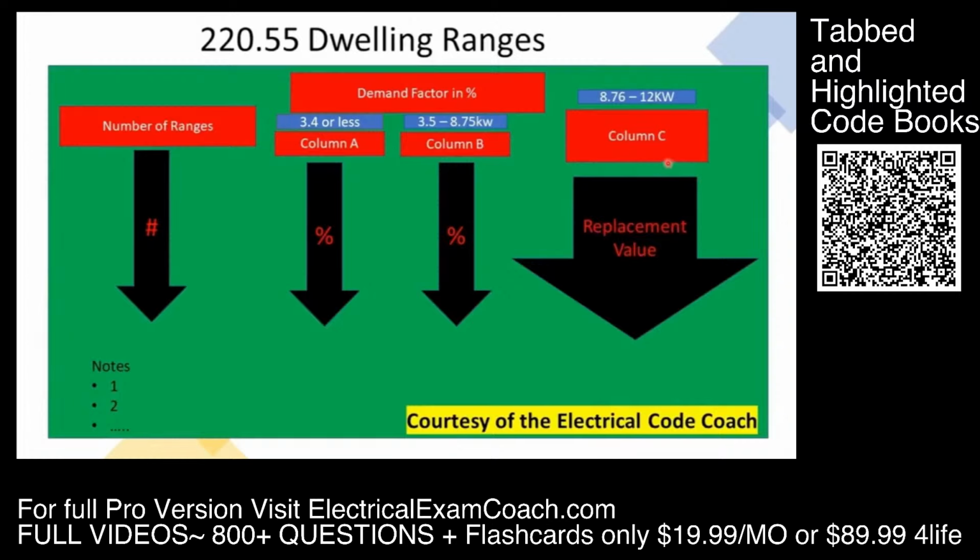Starting on the left-hand side in column A, this is when your individual range falls 3.4 or less kWs. In column B is when our ranges, the individual range itself, fall in between 3.5 and 8 3/4. Then column C is when our ranges are 8.76 through 12 kW. Then in the bottom left hand of the table, you're going to see some notes. And that's when we have a situation that doesn't fit into the normal table. And we're going to take it piece by piece. Let's get to it.